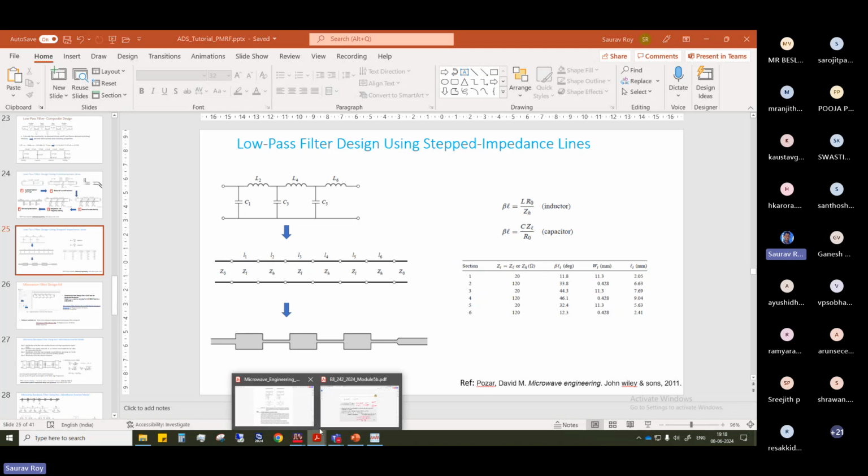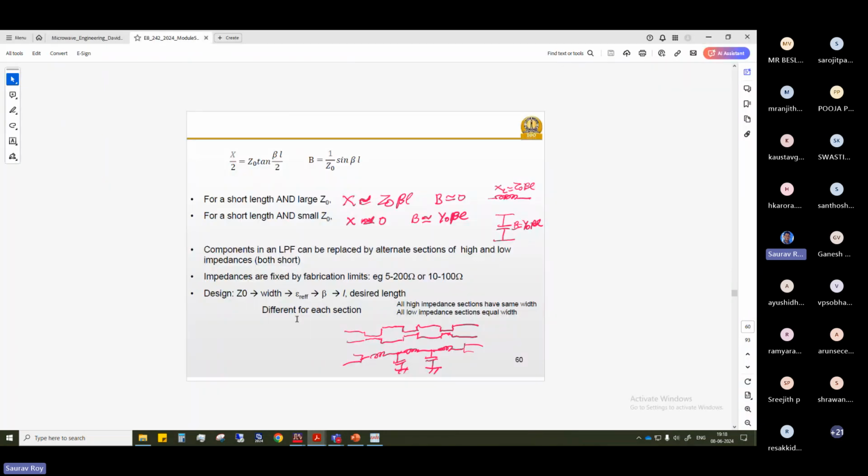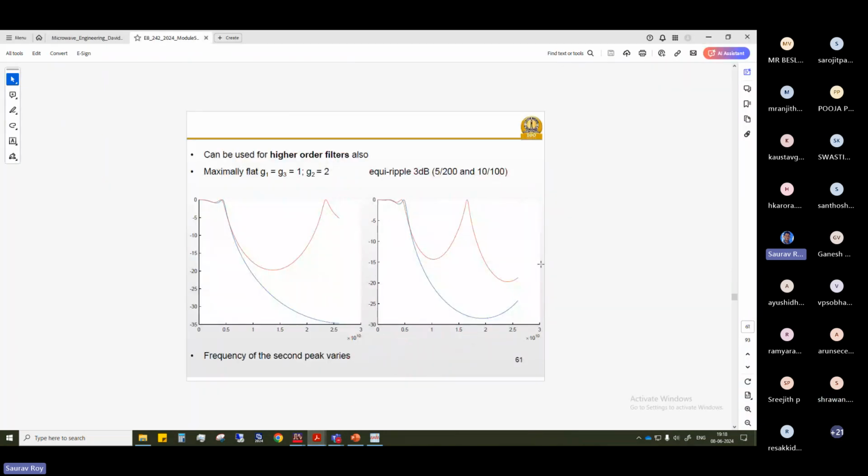No, it's not band reject. See, if you remember the theory again, see the simulations. It has been shown last week also. I told you, because microstrip lines and all those have periodic responses. So after some time it will again go up and go down. If you go to an even further frequency band, you will see this periodic response will come. And you can also say that it is one of the limitations of this kind of filter.